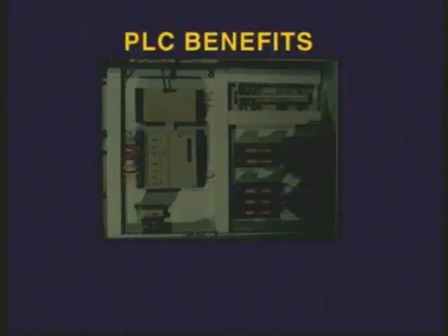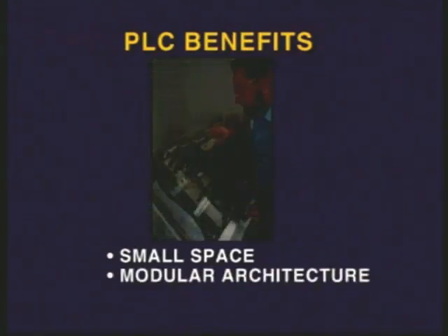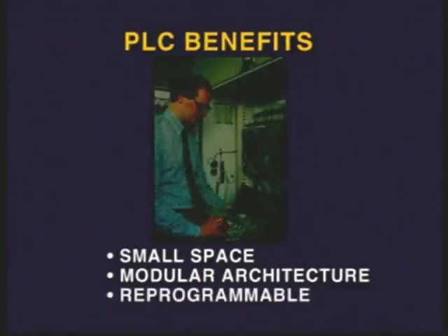Some of the benefits PLCs offer include the smaller space or footprint they occupy, the modular architecture of input and output modules, which allows it to virtually interface with all field devices, and perhaps the most important of all benefits, its reprogrammability, which simplifies changes and modifications in the field.